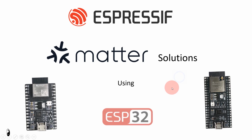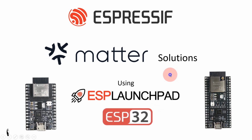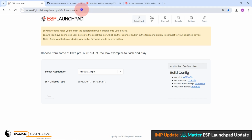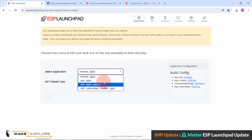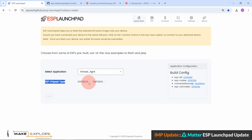So, in this way, we can use ESP Launchpad to program Matter applications into ESP32 and control them remotely. Here, please note that, while we were making this video tutorial, Espressif updated the Matter ESP Launchpad. Hence, there are some big updates. Previously, we saw that in Matter ESP Launchpad there were only 2 applications, Matter Light and Switch. But now there are 4 applications showing at the time of this recording in May 2024. They have also removed support for ESP32 and ESP32 C3 dev boards. Now only 2 dev boards are showing here, ESP32 C6 and H2. Let's hope they will add support for more ESP32 boards in future.